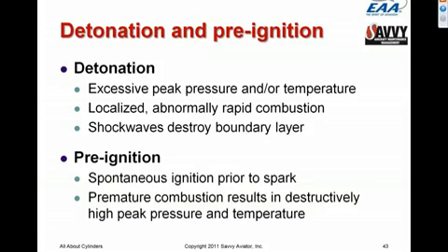But if detonation progresses far enough, it can start to compromise the components by exposing the cylinder head and the piston to temperatures that are above what they can tolerate, and they start to melt things, which is not good, obviously. Preignition is a much more severe situation.